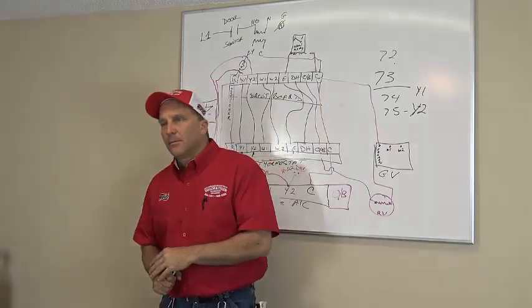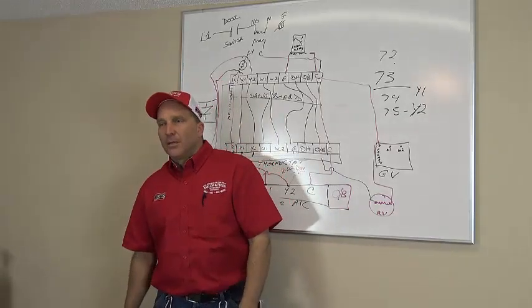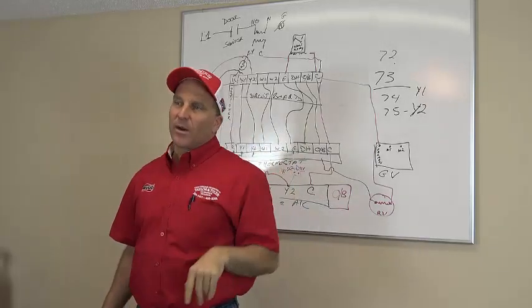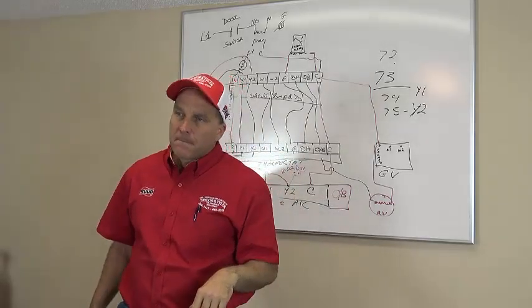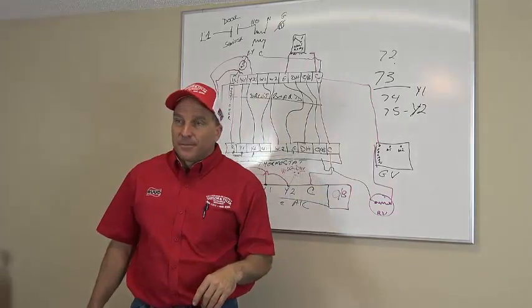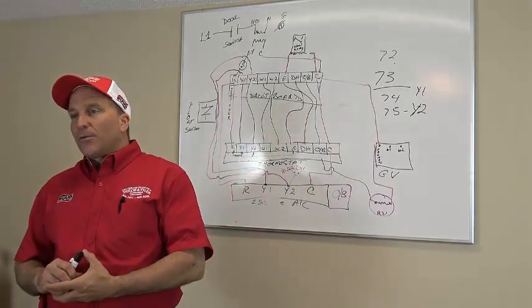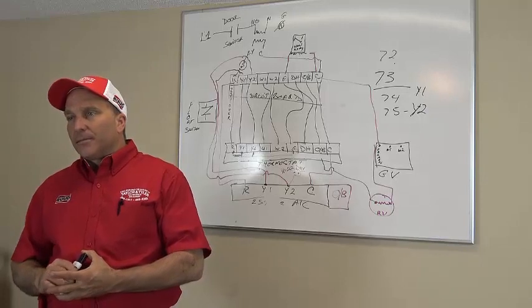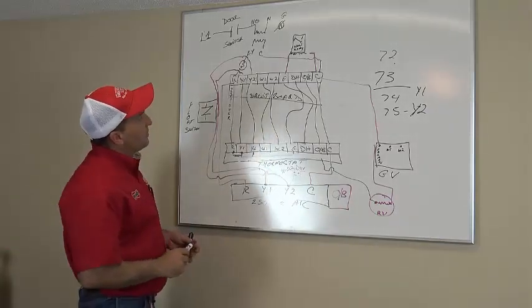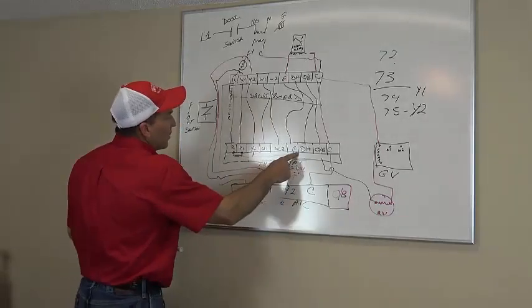Your pressures. Now your blower motor increased its speed, right? But your compressor's still running in first stage, right? So you need to check that. Check the pressures and temperatures, superheat and subcooling. Always goes back to refrigeration 101, doesn't it? Okay. Anybody not understand this so far? Okay, we're going to go to the next step.